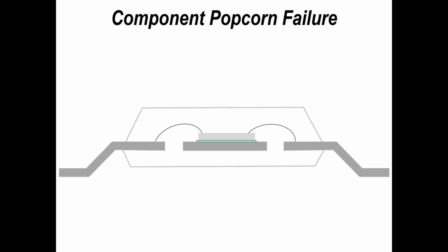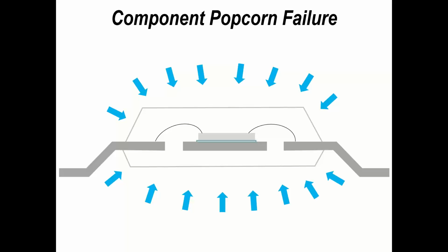So what fundamentally happens when you have a package, it's exposed to a higher humidity or moisture from some other source. Moisture can accumulate within the package, and you'll see a very small change if you were to weigh the part. But the moisture being present in certain areas, particularly if there are any voids within the plastic package, can cause the package to expand as it is heated. So what is actually happening is the plastic is being moved away from perhaps the lead frame, from the die, from the bond wires that I show in this particular diagram.